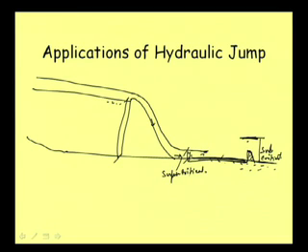So, ultimately between this portion, and of course some small blocks and other things are there, sometimes this approach is not that simple. I mean, a stilling basin has a lot of other things to do, but of course we are not covering that in detail. A lot of baffle walls, that means small walls, will be here in this portion itself. Some wall or chute block may be there, which will shoot the water in the upward direction. So, different things can be done here, but the main objective is to raise the depth and to form a hydraulic jump, and that way it shoots up from this part, and then it is going like this, and from here a hydraulic jump is occurring.